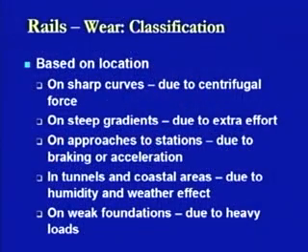So, this is another reason which may cause the wear. These are some of the locations due to which the wear of the rail section may take place, and as we have seen, not necessarily each and every reason may cause the wear at the same point; it may cause wear at different points of the same rail section.